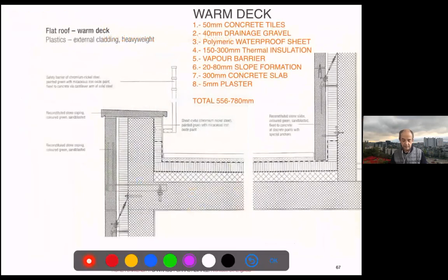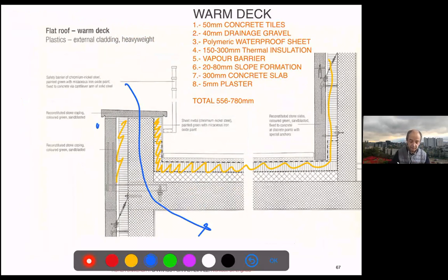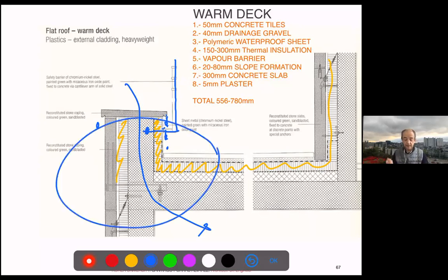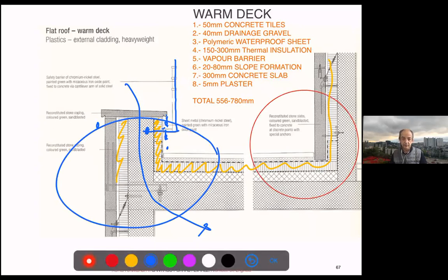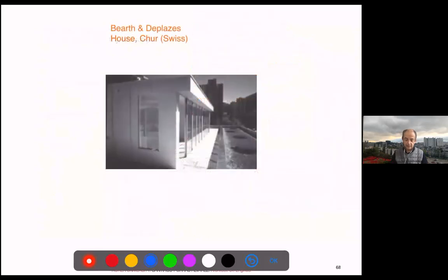So an example of a basement in which the insulation again is interestingly done with continuity, but again we have this thermal bridge. Intelligent point, well, you see the two drippers, right? When you have handrails, you will try to put them in a vertical connection so the water will have less opportunity to filter to the inside. And you have a protection from the dripper and the gravity working in your favor. Other elements, I let you see how they are done because they're quite interesting, right? Like the extension, the duplication of the waterproofing, and so on.